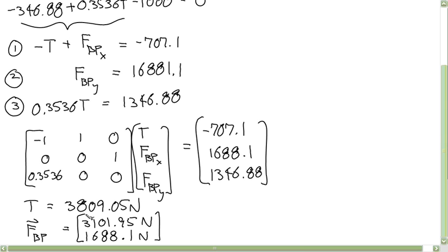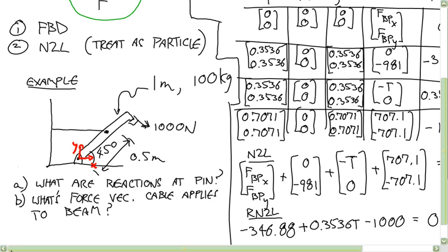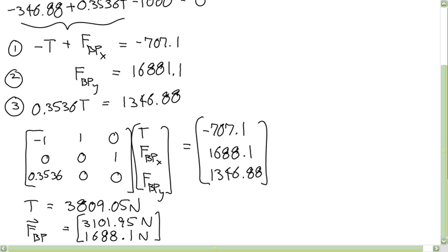What this calculation tells you that's interesting is, that doesn't look like a horribly odd way to rig a system up, but when you calculate those forces, you see that you're expecting that cable to hold a lot of force compared to the pin, which would be relatively stronger in most cases.